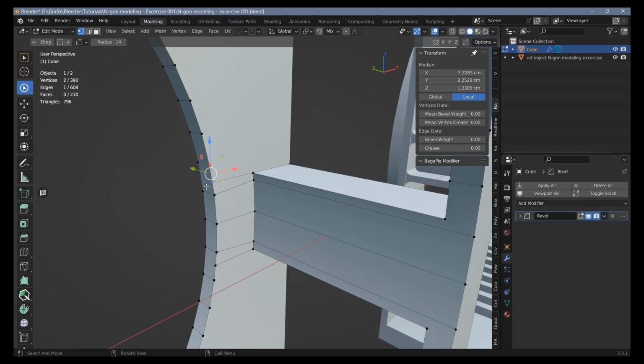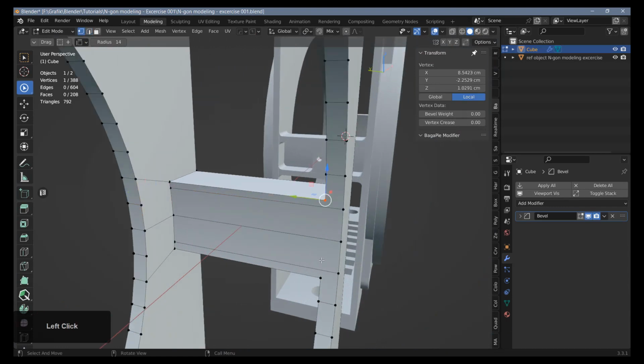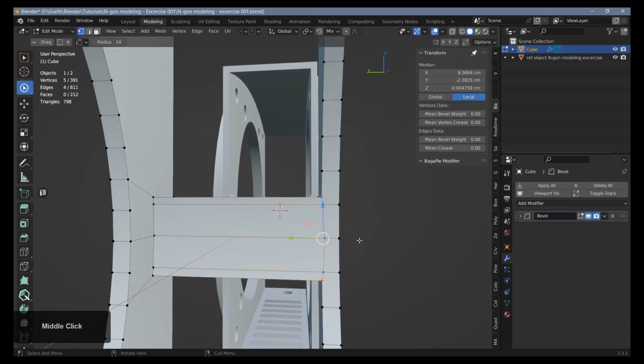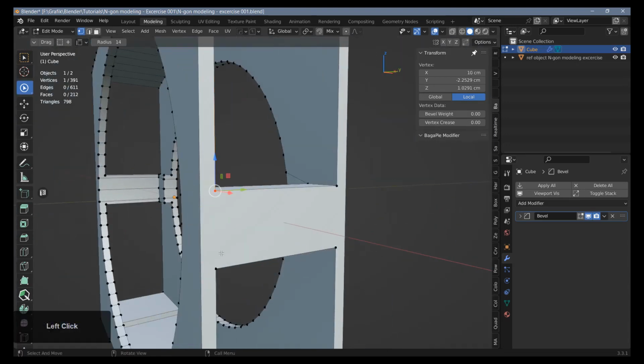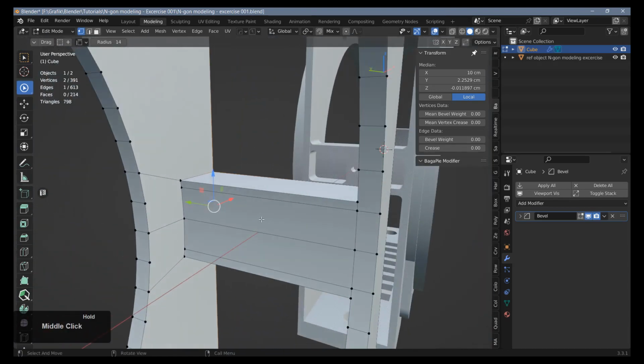And with these two verts selected, I can do a merge at last, and for this I have a Machine Tools shortcut, so I can do this a little faster. I'll do the same thing down here. And then I'll just dissolve the edges in between, like so. Now over here, I'm going to select these two verts, hit J to create edges in between, and again use Mesh Machine. It also has an align function that is really useful in order to line these vertices up. Over here, I'll select these two verts, hit J to create a connection here, and I'll also create an edge here. And there's one more thing I want to change.